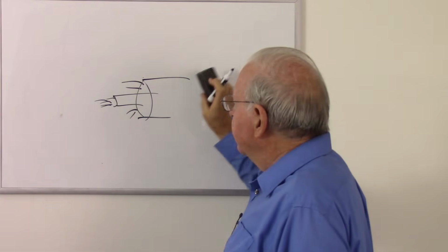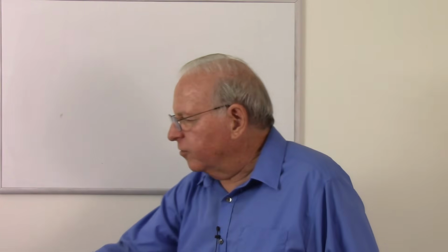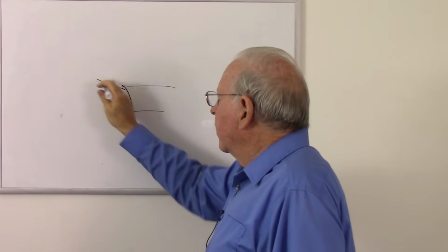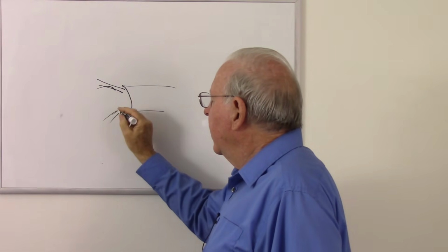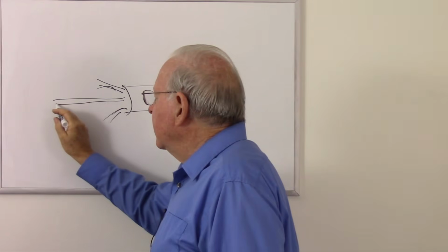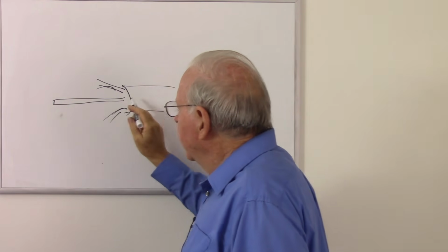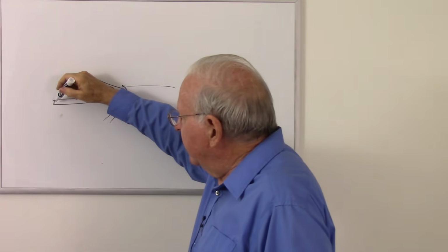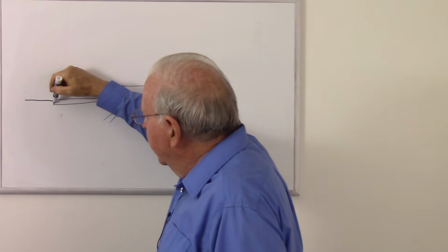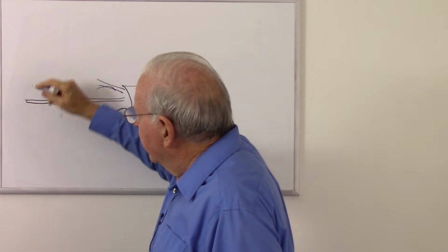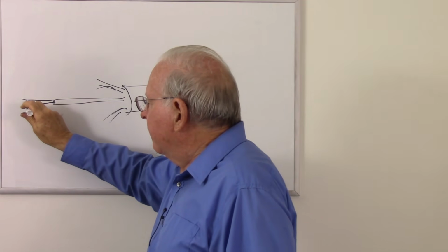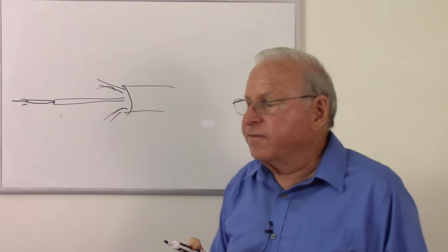And the next one we talked about was the tight buffered fiber, which is going to be such as, here's our jacket, our Kevlar, and then a single 900 micron buffered fiber. So our secondary buffer of 900 microns. Then inside that, if we strip back that secondary buffer, is our 250 micron buffer. And then we strip that, we have our little 125 micron fiber.